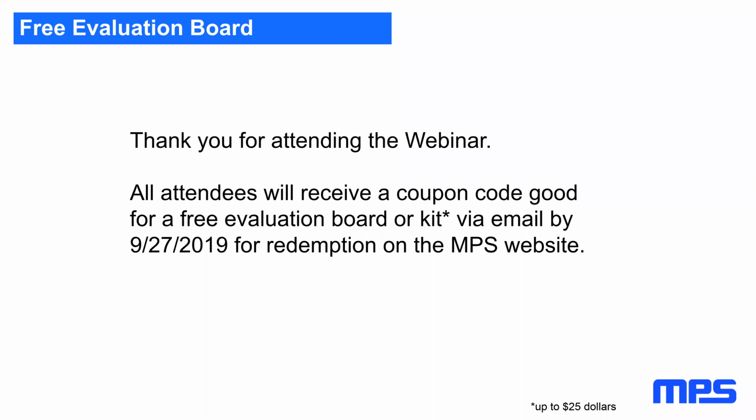From that, you pick a switching frequency, and you pick either an integrated switcher or a discrete switcher with external MOSFET, or you pick a module, and you go with your design from there. Because at a certain point, you have to deliver a solution to your boss, so you are only limited to what you can physically buy. So typically use pretty much the most modern stuff you can get your hands on. That's my recommendation.